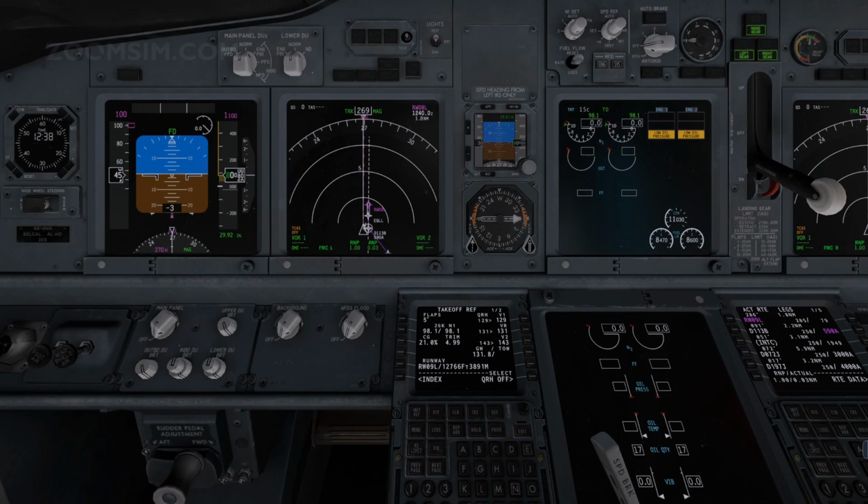In the outboard primary flight display position, the compact EFIS format is displayed on the outboard display unit and the inboard display unit is blank. In the normal position, normal EFIS and map displays are displayed on the inboard and outboard display units. In the inboard engine primary position, the engine display is displayed on the inboard display unit and the compact EFIS format is displayed on the outboard display unit. In the inboard primary flight display position, the compact EFIS format is displayed on the inboard display unit and the outboard display unit is blank.